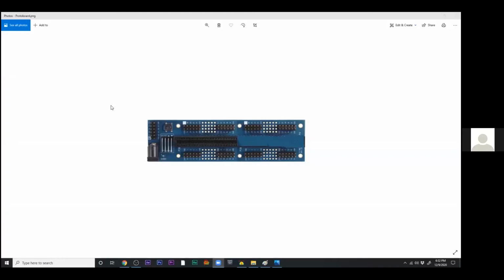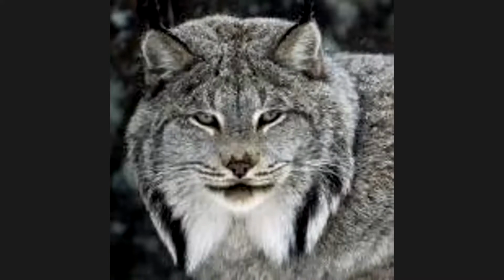Ken, while you're talking about that R&D, could I show you something here? Share my screen. Yeah. Why was the mini board limited to the I/O and not something like that? Oh, I see. Just because it's mini and not medium. All right. I was just wondering why it didn't bring it all out. Also, you had one too many of the 2x8 connectors, because there's actually 5 on the mini, and so you can only get 3 more, and you'll use all the IOs because the upper 8 pins are on that little connector that's by itself rotated on the side.